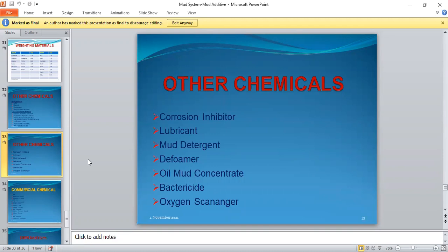That is completion. You want to carry out some rig operations or activities so that the oil will start coming out. From down to surface, you put your pipes, everything. You want to start bringing the oil, producing the oil, the juice, the gold, the pay zone. That is completion. So during completion, they mostly use brine, just salt and water. Salt and water will corrode your metals. So you use metal corrosion inhibitors.